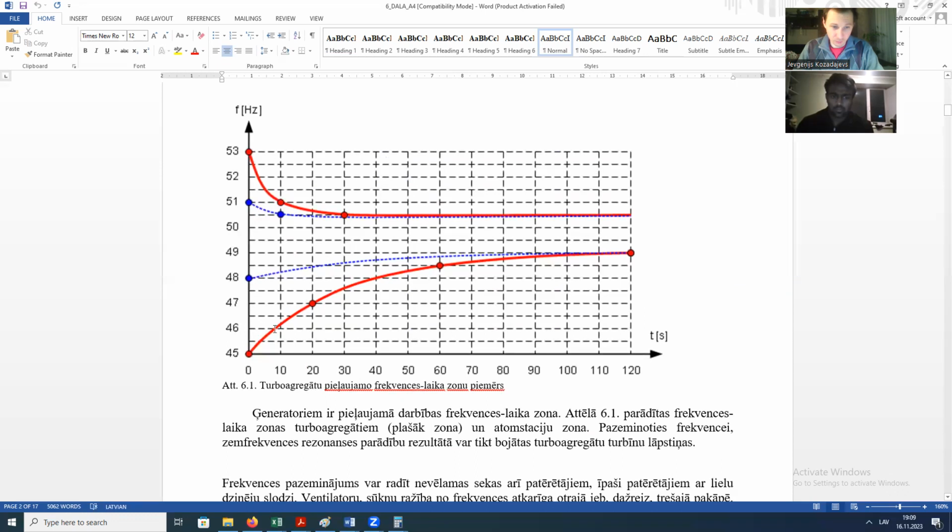Okay, it is possible to keep that for about, I think here, 8 seconds, but 45 hertz is impossible, yes? So if we have fragments of 45 hertz, it means we will lose all the generation. So if we have a deficit, we have problems with generation. And if we can't deal with this deficit and the frequency drops to 45 hertz, it means that we will lose all the existing generation as well. So the total blackout of the system.